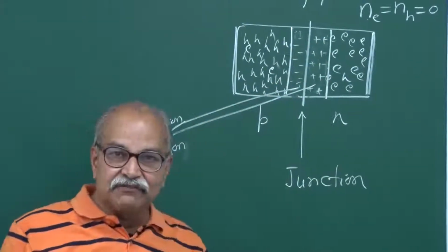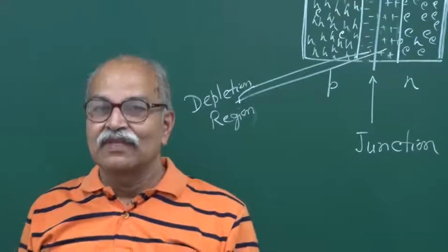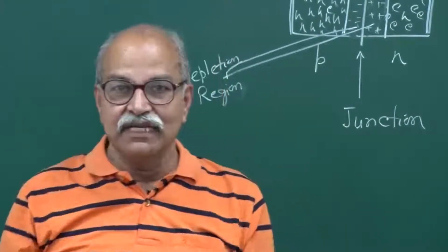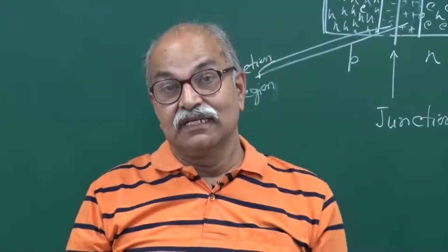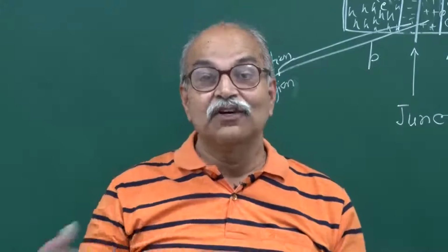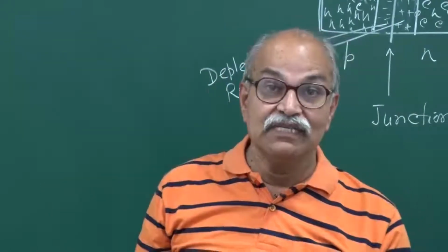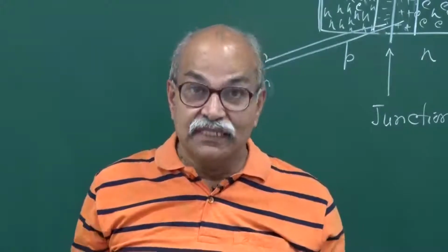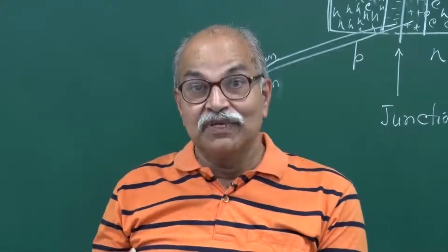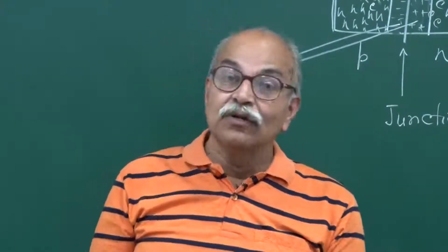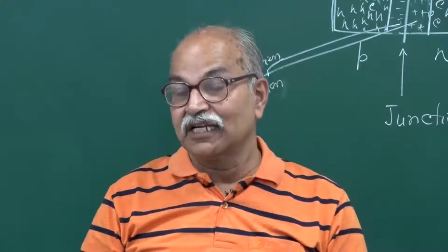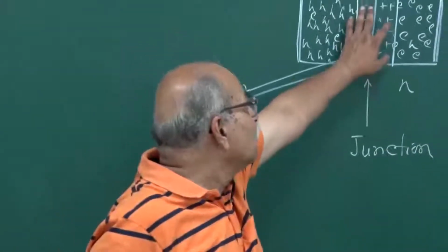But then at any temperature, as we told earlier, new hole electron pairs are created, because in that material you have thermal distribution. These electrons can get energy from the crystal of the order of the Boltzmann constant k times T. Because of that thermal distribution, energies are taken up, energies are given away. So new electron hole pairs are always created, and old hole electron pairs are destroyed in a normal semiconductor. That process is still here in this depletion region also.